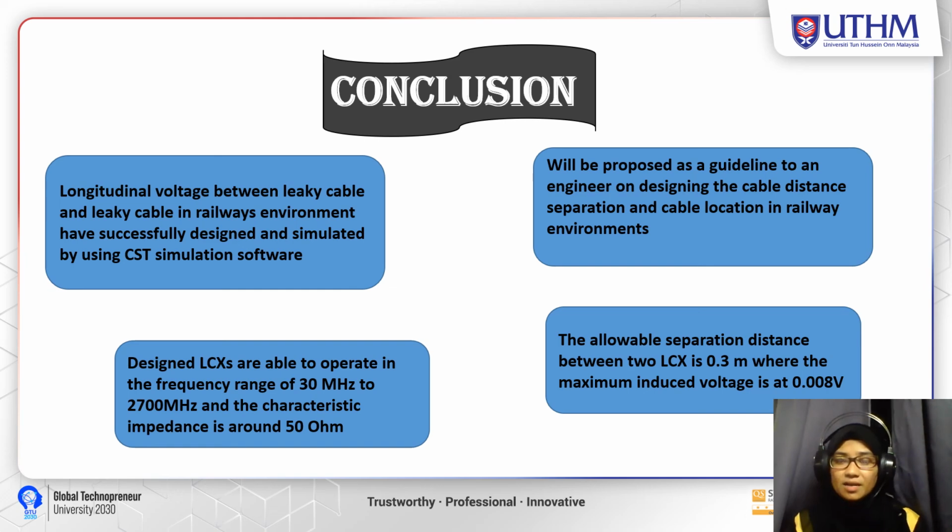Then, the allowable separation distance between two linking cables is 0.3 meter, where the maximum induced voltage is 0.008 volt. It will be proposed as a guideline to engineers on designing the cable separation distance and cable location in real environments.